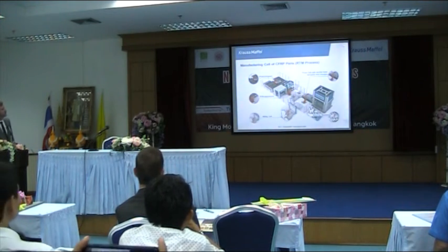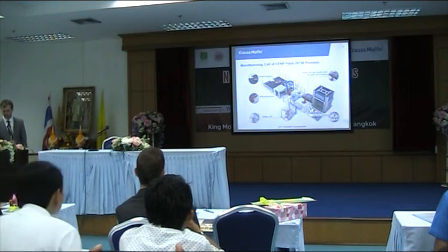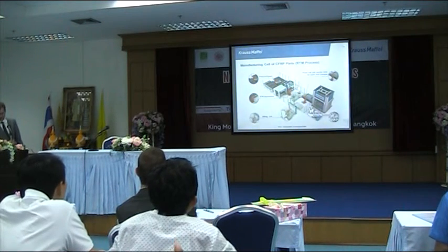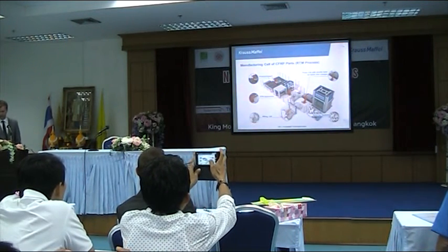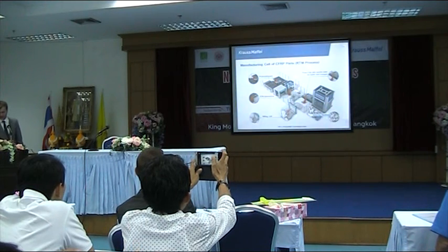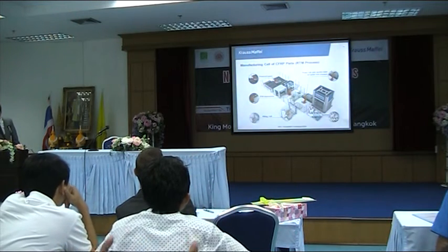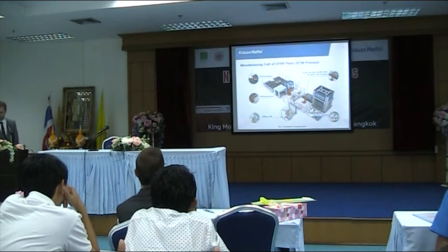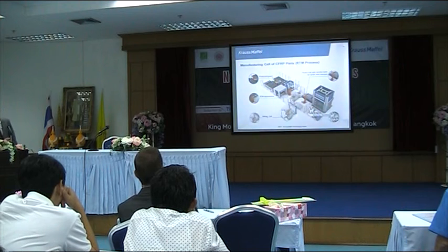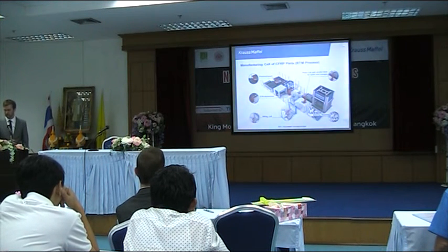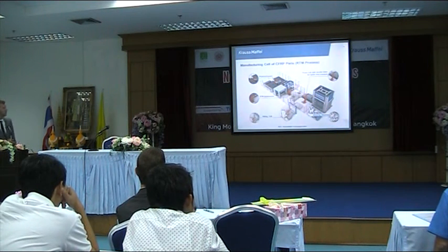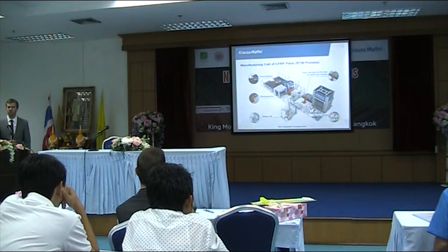So this is what you need to perform the process. You need the preform center where you prepare the preforms. You need RTM automation. You need, of course, a press cell here on the upper right, and shuttle tables for quick tool changes. Then you have the metering machinery, which mixes the isocyanate and the polyols and injects into the tool or the mold. And of course, you need some milling cell for finishing or for afterwards treatment.